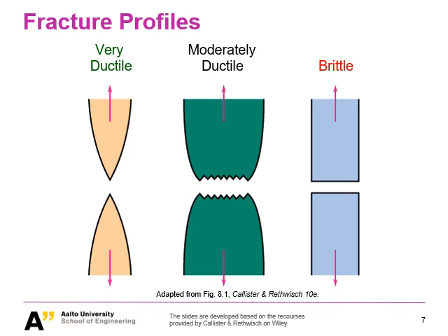Because there's another type of ductile, called very ductile. Here you can see you don't develop the cup and cone. You develop really a connecting point in the end, and these two connecting points just get separated from each other. If you zoom in to the structure, you can go to the two connecting atoms and you're just breaking their final atomic bond.